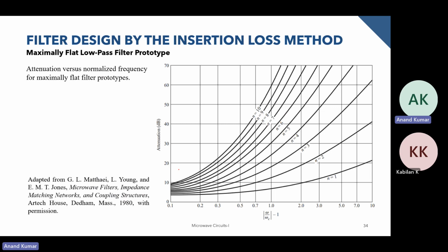And this is the plot for the frequency response, that is the attenuation with the frequency. You can see for a low order filter, the attenuation is pretty low, and if we increase the order of the filter, it becomes really high. But one thing that I have missed to stress is that if you increase the order of the filter, its complexity increases, and it is more difficult to include on the PCB that you're working on. If we want a better frequency response, we can always go to a higher order filter, but we need to keep the circuit simple as well.